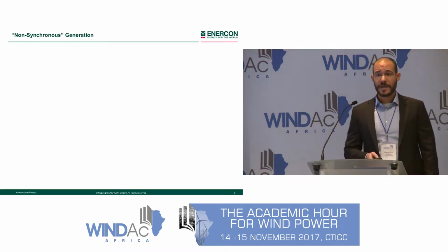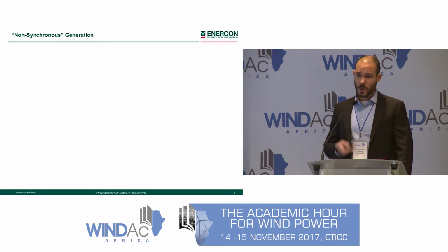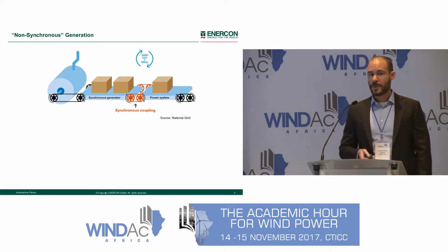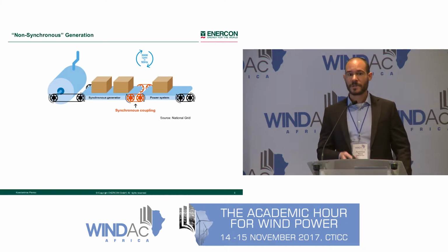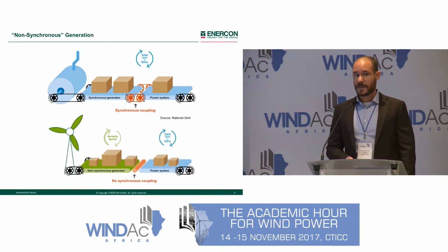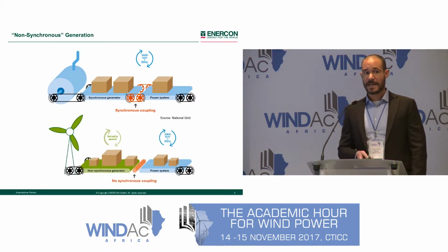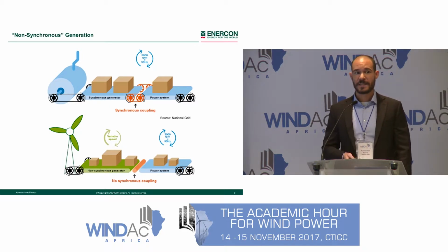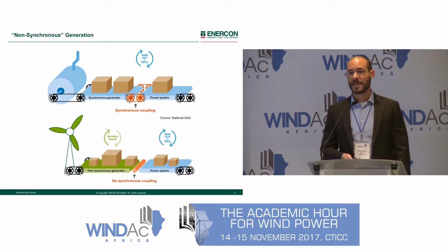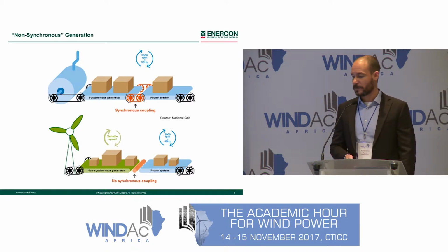State-of-the-art wind turbine generation is non-synchronous, in contrast to conventional generating units that equip most conventional fossil-fueled power stations. Modern wind turbine generators do not inherently react to frequency changes by adjusting their active power output. Unless they are fitted with additional controls, their inertia constant can be considered negligible.